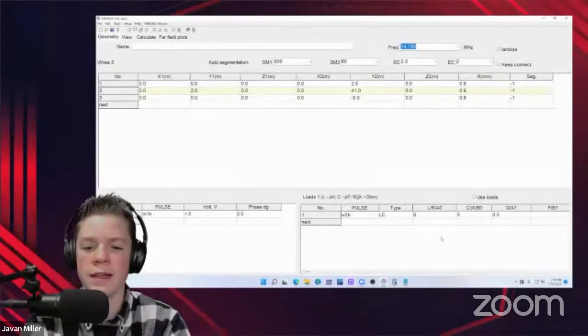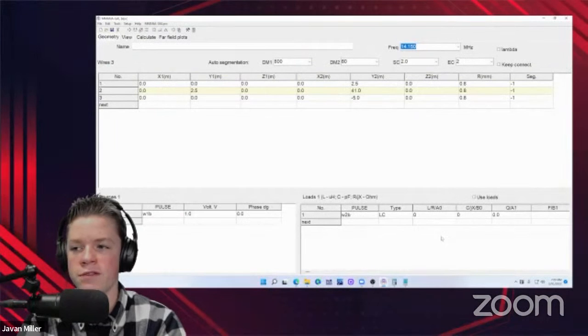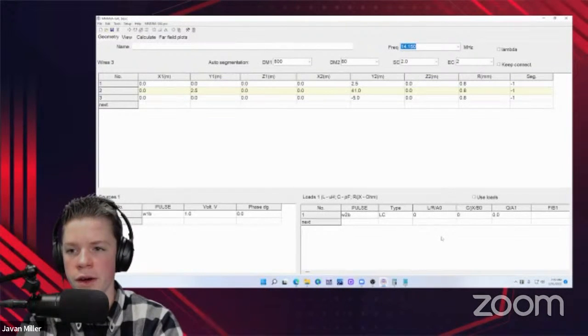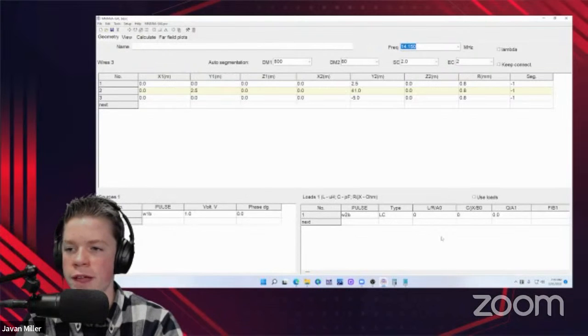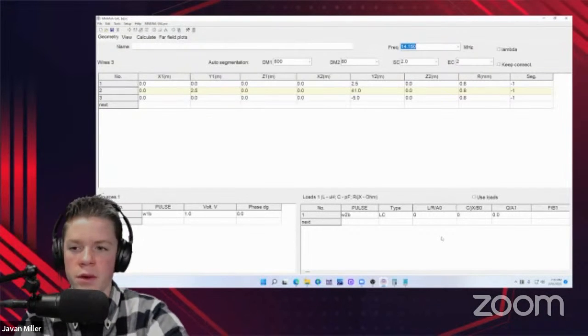Okay, I was thinking that was further out, but is that basically to act as a choke to cut the antenna's equivalent length down at the higher frequencies? There are some designs with traps in these end-fed half-waves, but that's not what this is doing. This is not a trap. It's just an inductor that has more effect at the higher frequencies than it does at 80 meters. So that's what this is doing here.